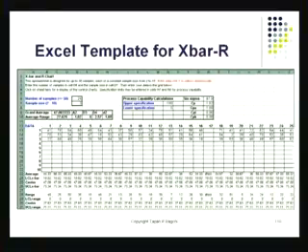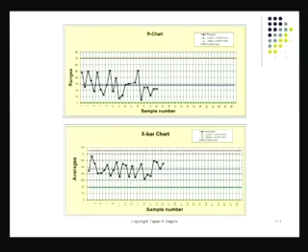Then he would pick up the next blade, and that blade would have the same fate: machining, measurement, machining. Then he put that blade aside, again made the measurement data, and entered the data there. Then he did his X bar calculation. Then he did his range calculation. And then, would you believe, he plotted a few points on the control chart. The top half was the data, the bottom half was the chart, and every time he took a blade out, he did this.